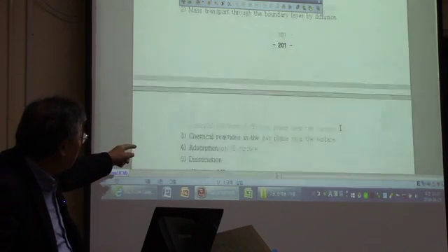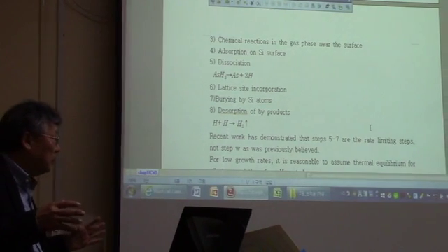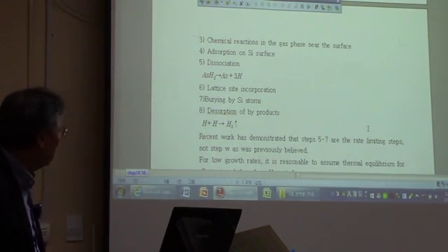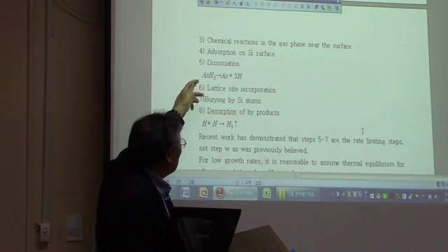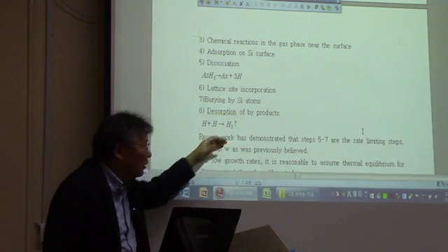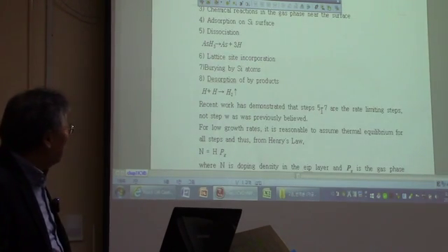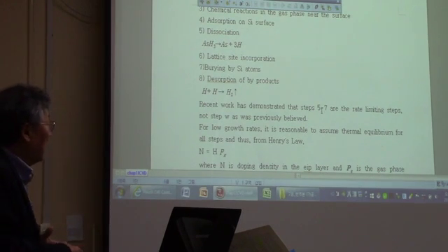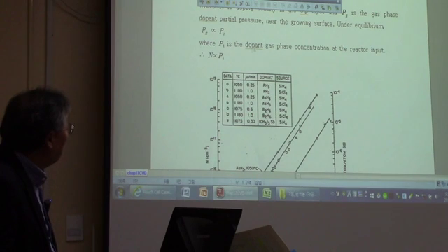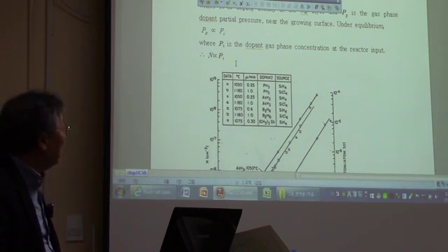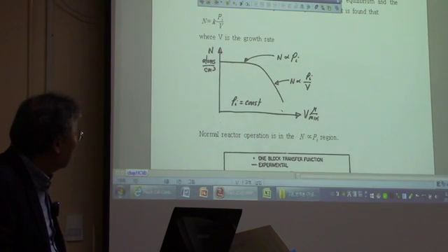And the steps here, 1, 2, 3, 4, 5, 6, 7, 8, are more or less like the steps taken for the epitaxial layer of silicon. The only difference is the dissociation reaction of the dopant gas and the incorporation of the dopant into the silicon site. Okay, and it takes the substitutional site. So, except for the fact that the silicon is replaced with the dopant atoms, everything seems to be the same. And obviously, the dopant concentration in the epitaxial layer should be proportional to the dopant gas partial pressure. Of course, that's intuitively obvious.